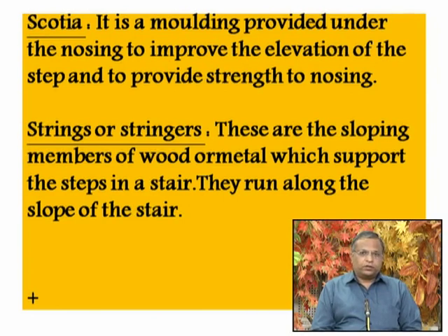As you see, the nosing is a projected part. So at the bottom of that nosing, there should be some support provided, and that is known as a scotia. It is a molding which is provided under the nosing to improve the elevation of the step and to provide strength to the nosing. That part is known as a scotia.